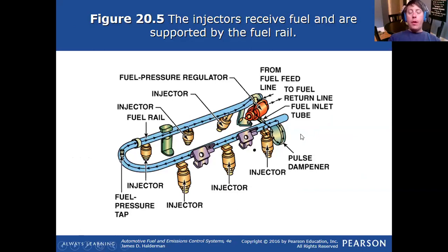Which reminds me, one more thing here. Think about the flow of the fuel in. On your returnless systems, keep this in mind. If you have a situation where the vehicle experiences junk moving through the fuel rail because the filter didn't pick up on it or the filter degraded in line, if it's a returnless system, typically the last injector in the line is the one that'll collect all of that junk.